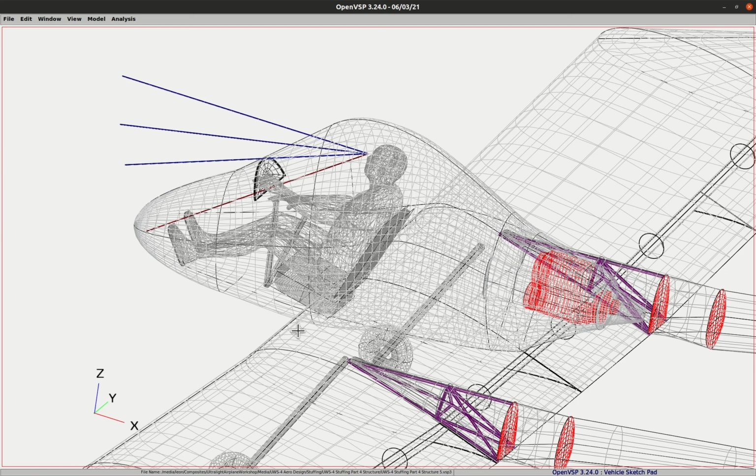So what's going to happen to a composite fuselage when that happens? Let's say you hit fairly hard on the nose. That composite fuselage typically, now this isn't going to be true for all fuselages, but typically that fuselage is going to fracture, and you're going to get sharp ends of any beams you have in here that break, and those could easily impale your body. Now with steel tubing, they could bend, but they typically won't break and then have sharp ends that can impale you.